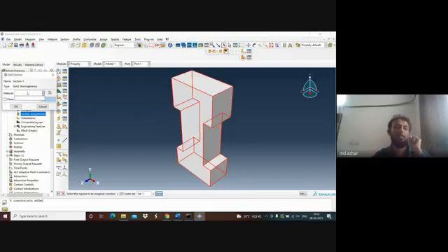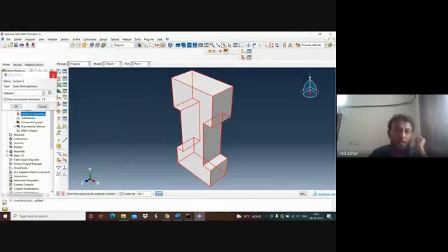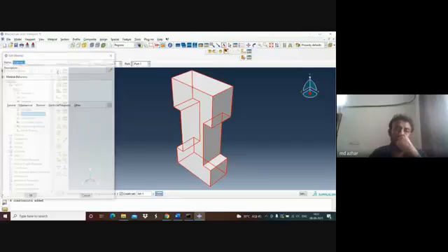Now let us give the thickness here. Let us provide the thickness as 1.5, and let us continue. So now you can see that it's showing missing values. Missing values means no material has been assigned to it. So now we go to the material domain. We can also do this before. So before this section, I can cancel this section, and we can go to the material domain.